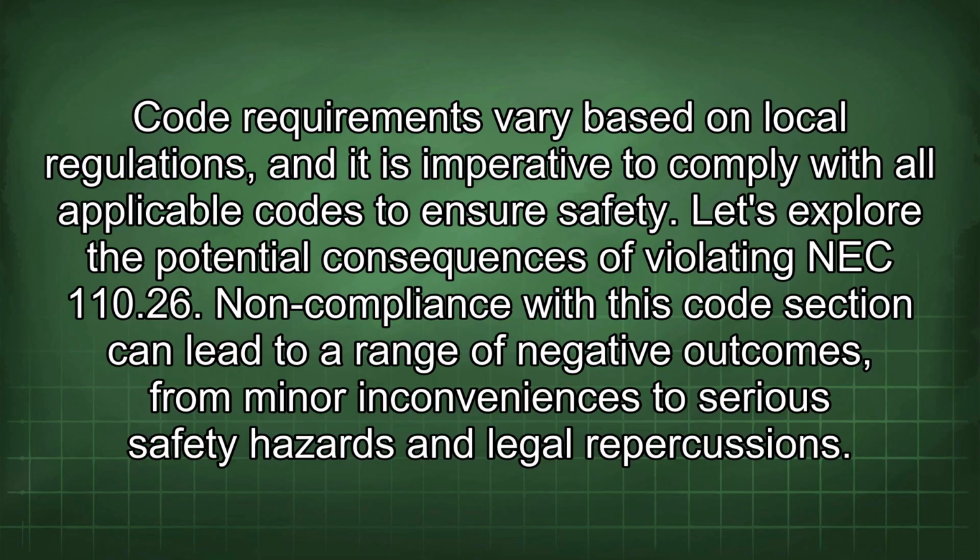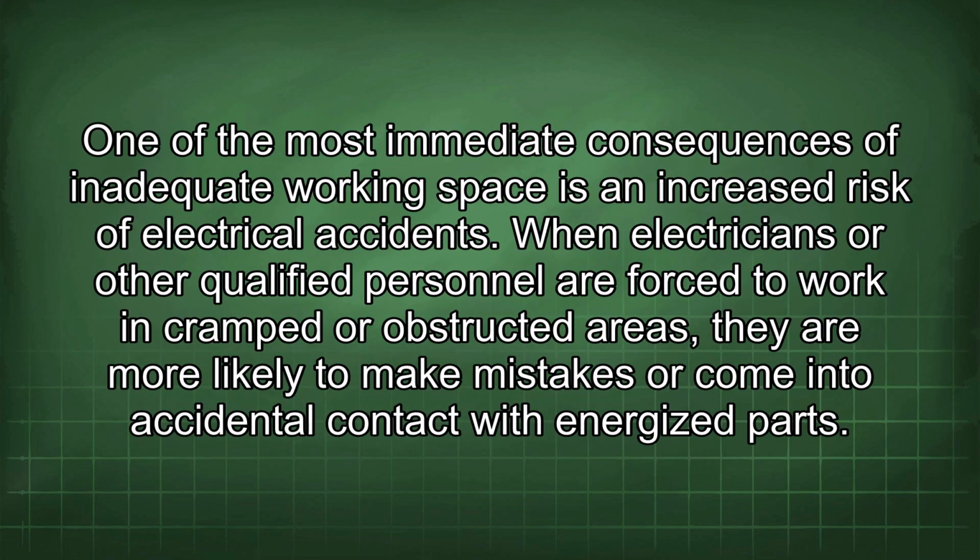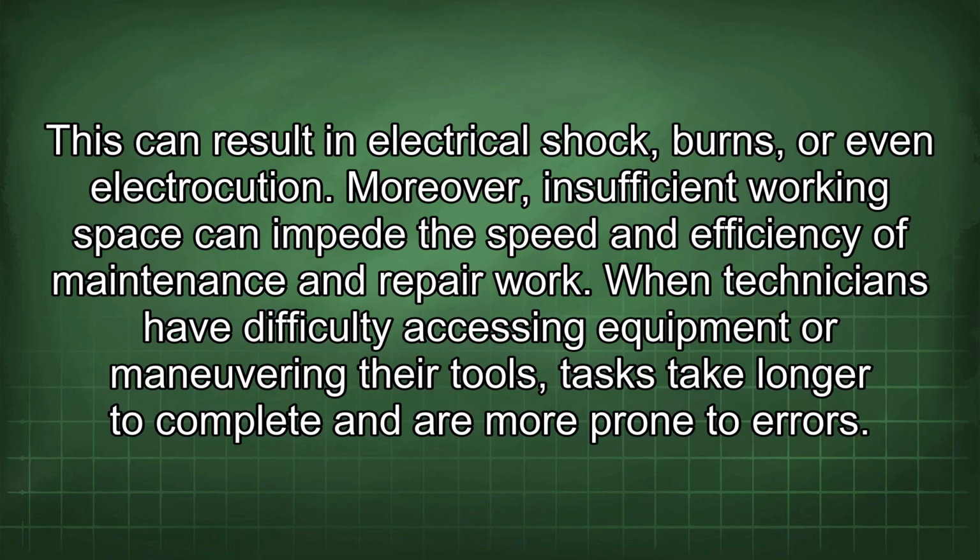Let's explore the potential consequences of violating NEC 110.26. Non-compliance with this code section can lead to a range of negative outcomes, from minor inconveniences to serious safety hazards and legal repercussions. One of the most immediate consequences of inadequate working space is an increased risk of electrical accidents. When electricians or other qualified personnel are forced to work in cramped or obstructed areas, they are more likely to make mistakes or come into accidental contact with energized parts. This can result in electrical shock, burns, or even electrocution.